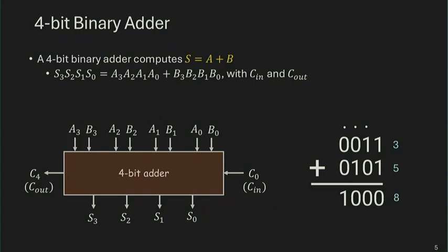The circuit also has a carry in. Right? Even though typically when you do 4-bit addition, you don't need a carry in at the very beginning. But think about concatenating this adder with another 4-bit adder. Having that additional carry in allows you to put multiple copies of this 4-bit adder back to back to create a wider adder. So it's like a part of a modular design. Having that carry in allows you to put together multiple 4-bit adders to build an 8-bit adder, 16-bit adder, and even 32, 64-bit adder, etc. And hopefully, I can send in my 2 4-bit inputs, let's say 0011 and 0101, at the A inputs and B inputs, and get my sum at the bottom.